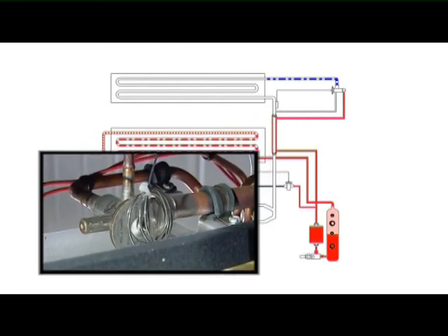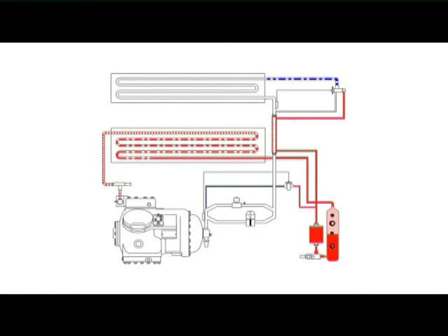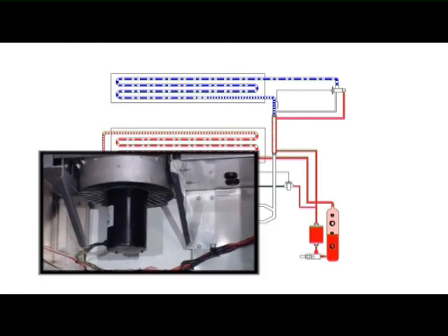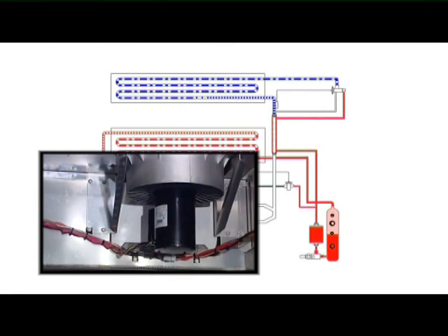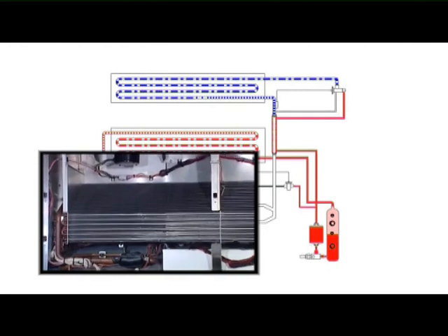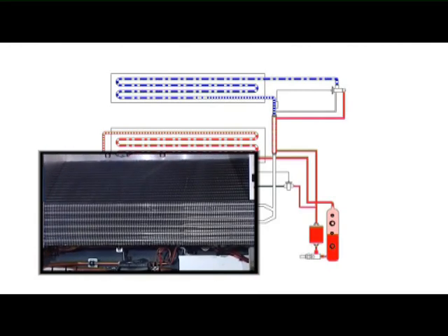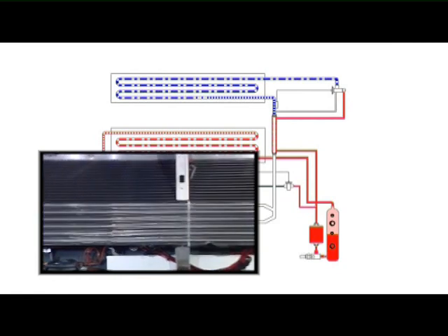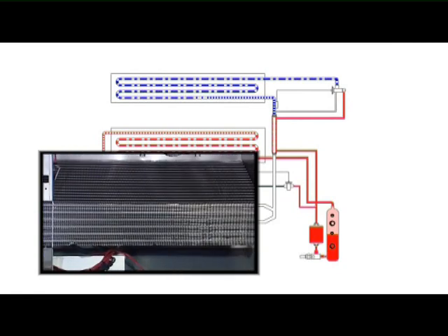As the refrigerant passes through the TXV valve, there is a pressure drop from the high side to the low side of the system. The low pressure and low temperature saturated mixture from the TXV valve enters the evaporator coil. The air circulating over the cargo by the fan motors is also circulating through the evaporator coil fins. Heat from the cargo is transferred to the refrigerant inside the evaporator coil. Heat is absorbed, causing the refrigerant to boil into a vapor.